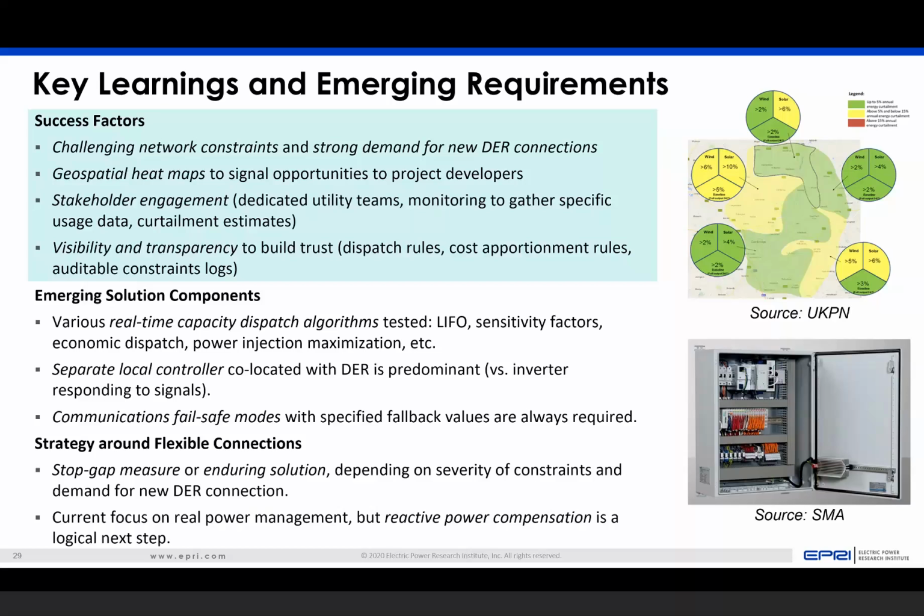Third is that engagement with stakeholders and project developers is really key to success for these agreements. This is new to many different stakeholders, so ensuring that they all have a good understanding of how flexible interconnection works and how much curtailment they can expect is really important. Many utilities who are early adopters of flexible interconnection have organized dedicated teams to focus on these agreements to help maximize the engagement with the various stakeholders associated with them.